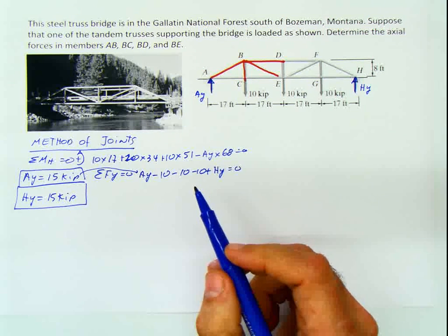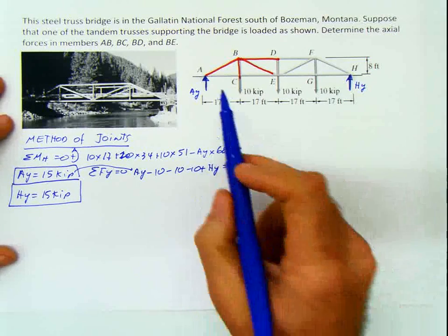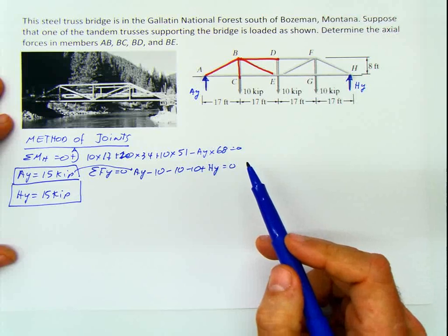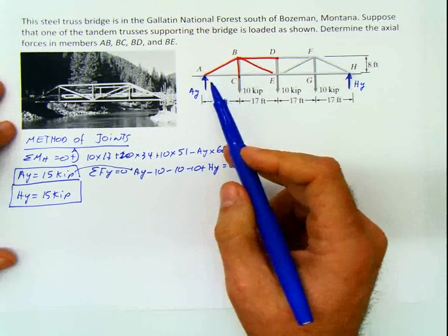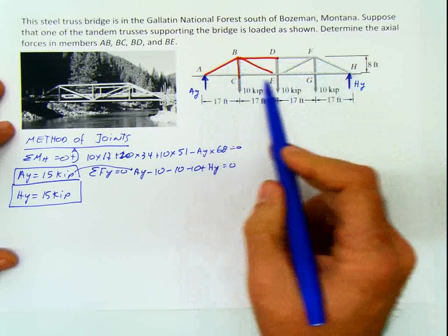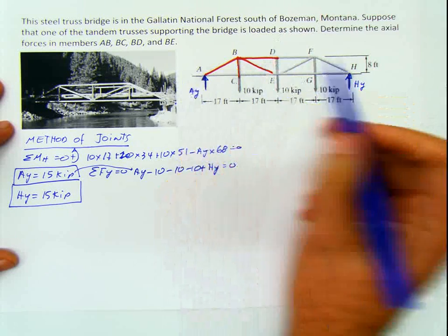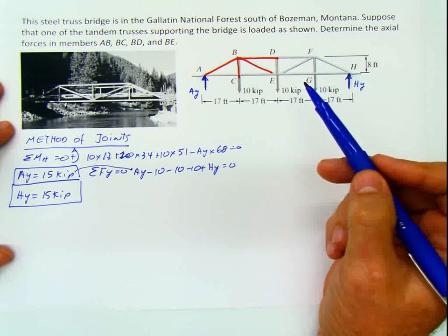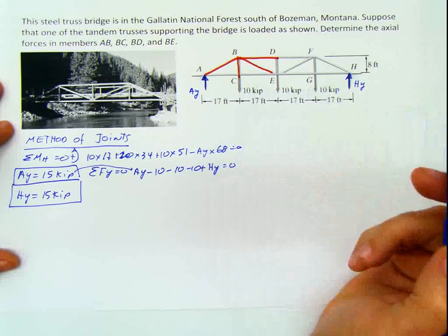So we calculated the reactions, and we already wasted time by doing that. Because if you think, instead of starting to work, you will realize that this structure is completely symmetric regarding the geometry. All the distances are the same spacing. If you draw a line here, it's exactly the same on both sides. Everything is symmetric, geometry wise, and at the same time everything is symmetric load wise.